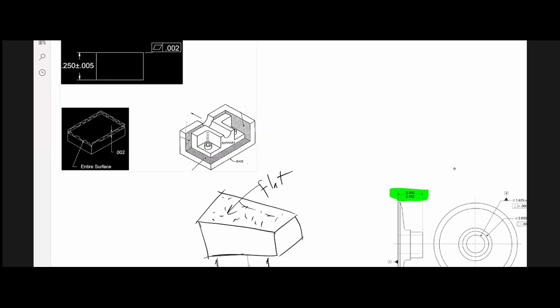The algorithm will find the optimal surface that goes through all of the points, rotate it until level, and then test it. There are also 3D scanners, and some non-contact CMMs that are in a way 3D scanners. I know you did CMM in 322, but I'm just reminding you. If you're using dial indicators, then you do have to level it.